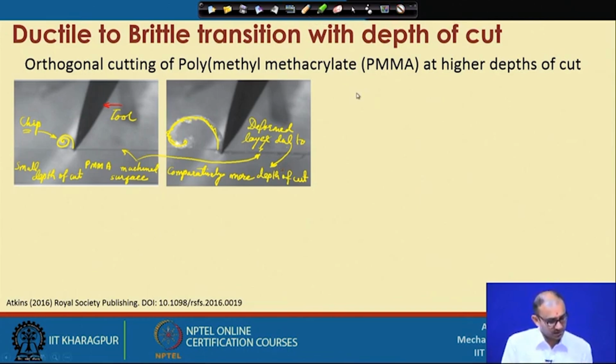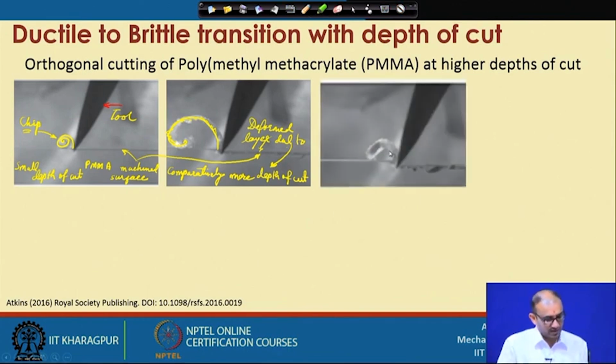Let us increase the depth of cut a little bit more. Now we are going further down into the material, and you can see the removal of the chip is a little more difficult. In the first, second and third one, you can see that now material is not removed very efficiently. The chip is not of a curvy nature, but some of it is very bulky and some of it is very thin. This one is very bulky, and here you can still get one curvature, but see the machined surface deformation, it is very prominent here. So it is not efficient cutting. Let us further increase this.